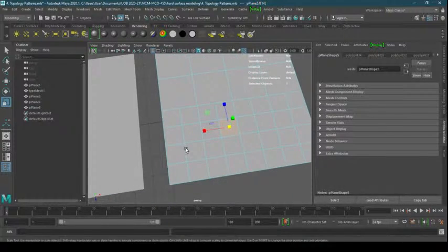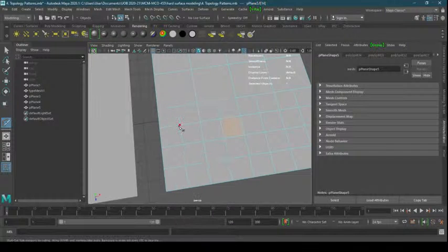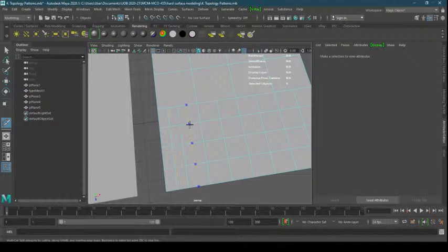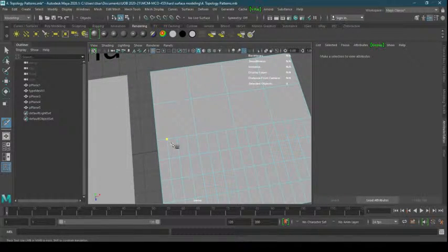How can I fix this? I will right click with the shift key, go to the multi-cut, press Control on the keyboard, and add one here, one here with the middle mouse button, so it will make it in the middle. Once I'm done with this, I want to continue this one till here, but it's not continuing because of the less space, because of the unmatching faces.